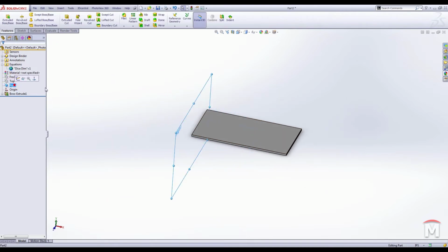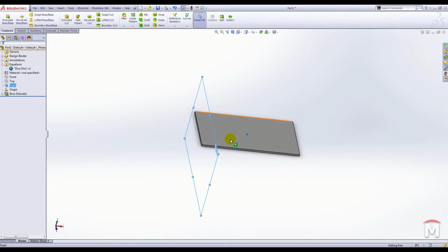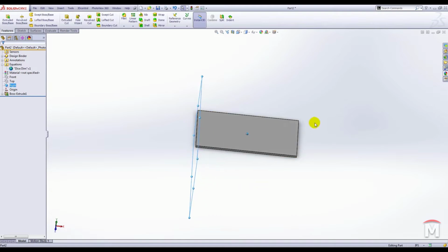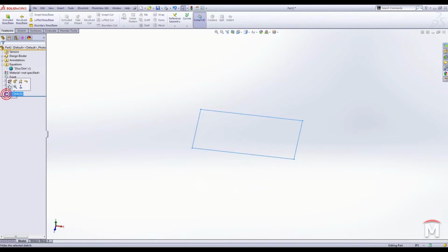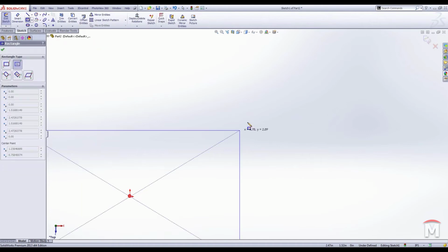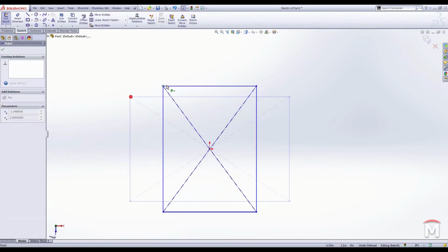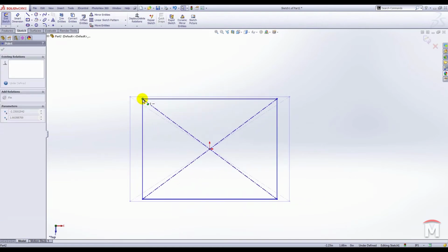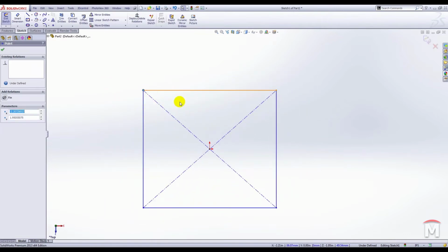If we need to use that center point for anything like mirroring features or doing anything like that, well, we have a problem. We can't do that because everything is based off of that 0 coordinate and moving over here in positive space. So I'm going to go ahead and delete that and edit that original sketch and just get rid of this guy. Alright, so what I like to do is use a center point rectangle. I'll start right at the middle and start drawing that guy. Since we are dealing with a dice, it's essentially a cube, I want to make sure that the top and the sides are equal here.